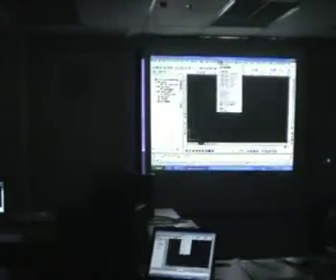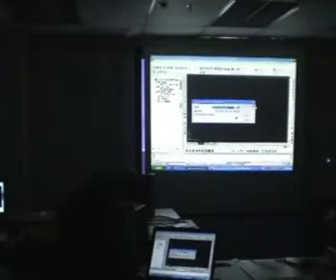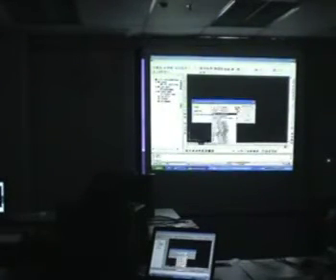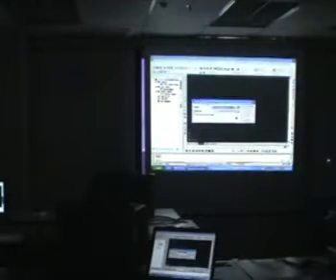So when we import this, we just go to points, import points. And this is where we specify the format of the file you want to import. For Land Desktop, this is the list of default formats that comes with the program. ENZ, for example, stands for Easting Northing Elevation. We've got comma delimited, space delimited. This delimitation just means what separates one column from another. In this case, it's a comma. Sometimes you may come across just a space, or maybe a lot of space. So at least you can use space delimited in that case.